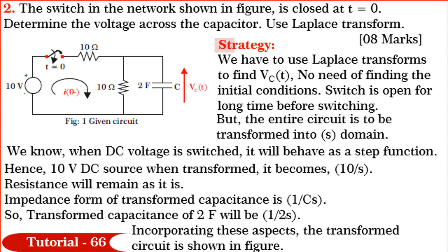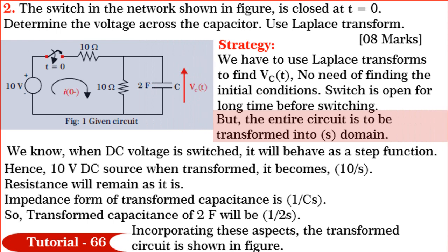Friends, first let me explain the strategy to solve this problem. Since we are required to use Laplace transforms to find Vc(t), there is no need of finding the initial conditions. Understand this. But the entire circuit is to be transformed into S domain, friends.